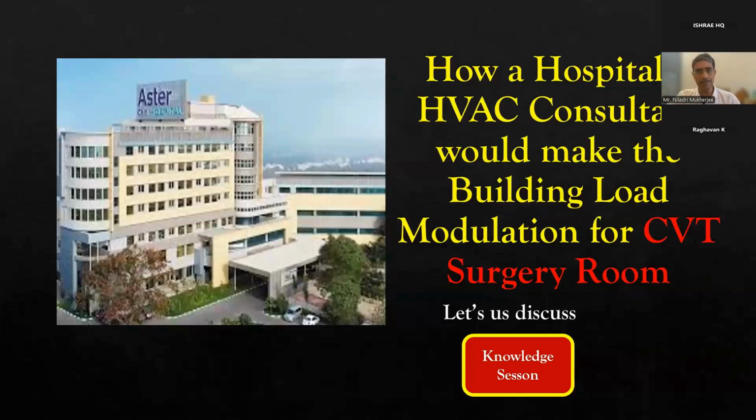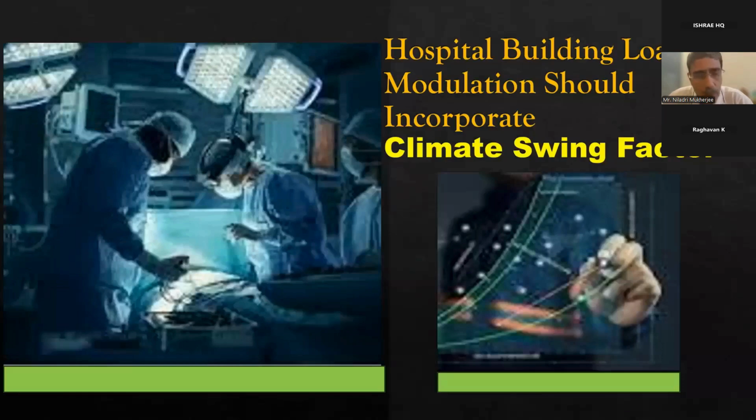This is a very important factor that is called the climate swing factor. Now, in India, there is the National Building Code. They have made 5 zones: hot and dry, warm and humid, something like that. Most of North India, from Delhi through UP and this area, is either hot and dry, or very hot, or averagely hot, and the temperature change between winter and summer is very high. This is called the climate swing factor.